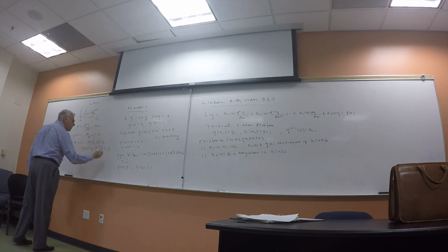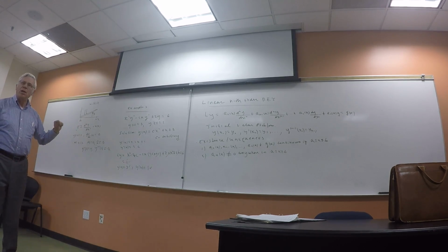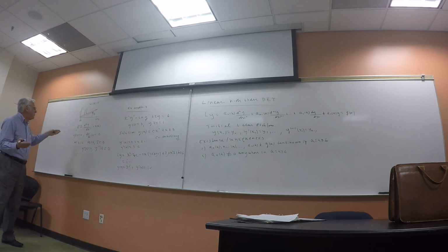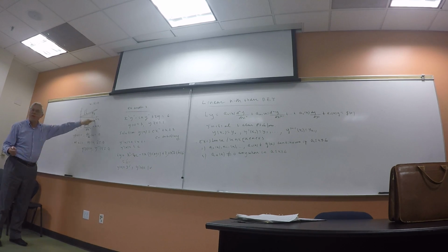Okay? So what happens here is that we have a fourth order equation. Okay? We have 4 conditions, but because of the physics of the problem, they're naturally going to be specified at 2 different points: 2 at the root of the beam and 2 at the free end of the beam.